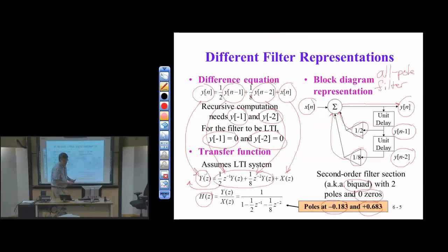So in the previous slide, again, if you remember, we had exactly these terms. This is exactly the left-hand part of the biquad, except that now this 1/2 is really A1, and the 1/8 is really A2. So that's A1, and that's A2 more generally in the biquad.